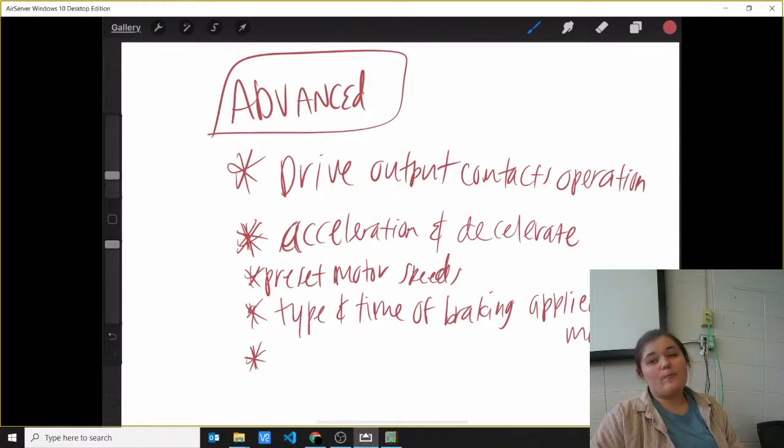But I'm pretty positive, depending on the VFD program software that you would buy, like if you bought an ABB or whatever, it would come with its own programming software that you would download and then literally just do it all on your computer, iPad, whatever, and then download it to your VFD if it was advanced.